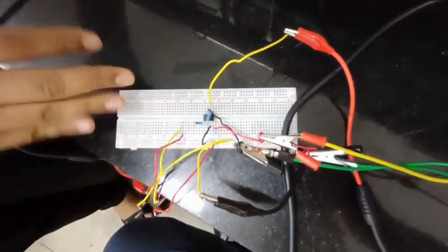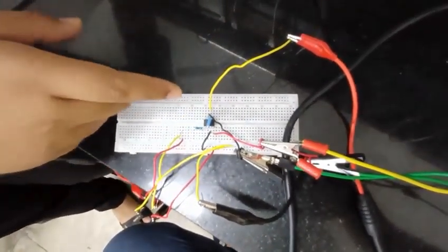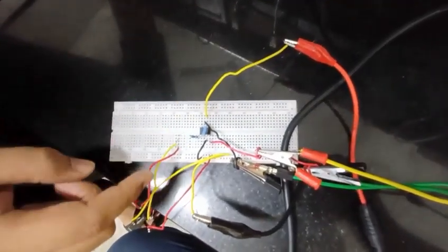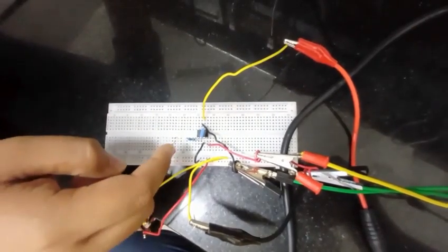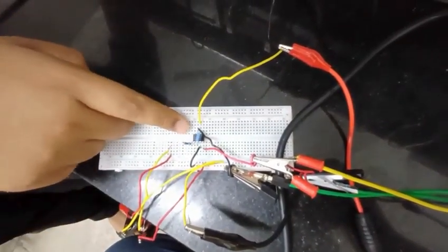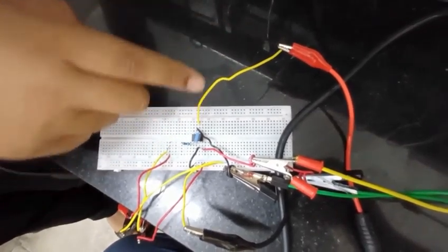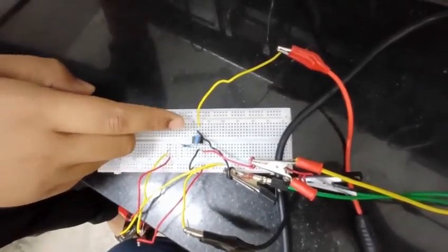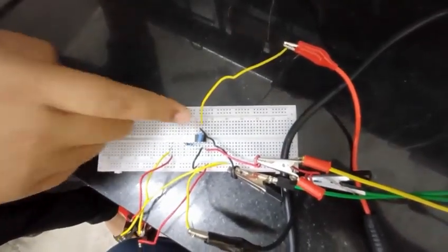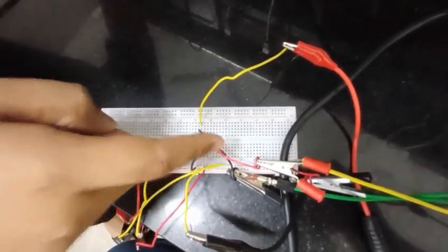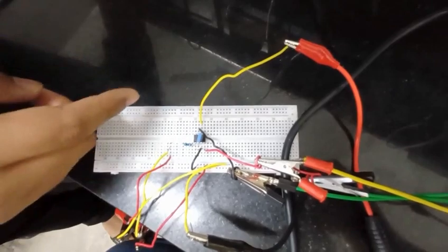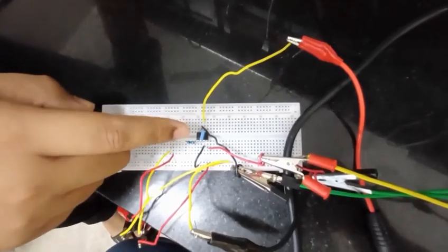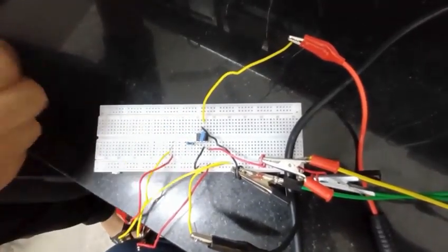Here, as you can see, in the integrator circuit which we have made, the resistor which we are using is 1 kilo ohm, and the capacitor is 100 nanofarad. The red wire is the input voltage, and it is connected to the inverting terminal of the op-amp via the 1 kilo ohm resistor. The output terminal of the op-amp is connected to the inverting terminal via the 100 nanofarad capacitor. The black wire is plus VCC and the red wire is minus VCC, which are plus 12 volt and minus 12 volt respectively. This line is grounded, and we are connecting the non-inverting input terminal of the op-amp to the ground.